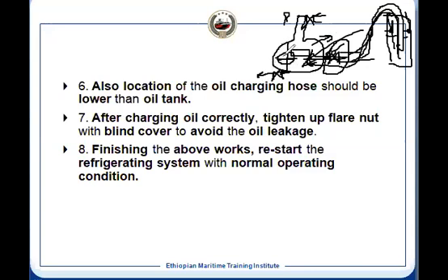has to be shut, and before that there should be flushing of the oil. So you use the oil, don't put back the cover. Before that, you will have to flush with the oil. You will have to flush the internal surface of the crankcase, and also on the bottom there is a little flushing, and after that you shut the drain valve. After that, you fill up the oil with the can, and you check that the oil level is the required level. After that, you close it, and then you restart the compressor.